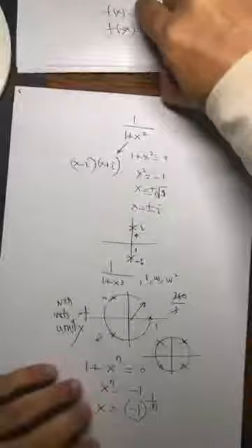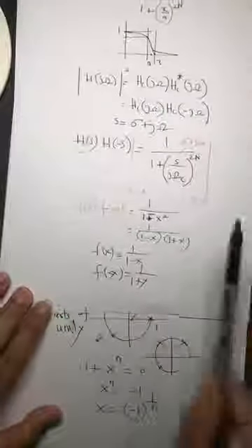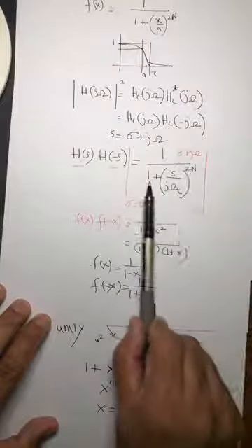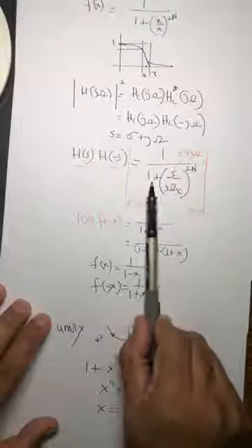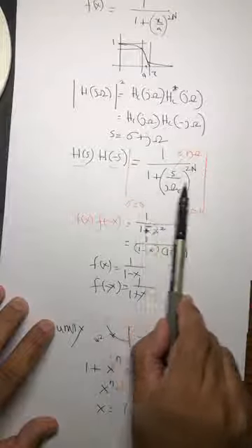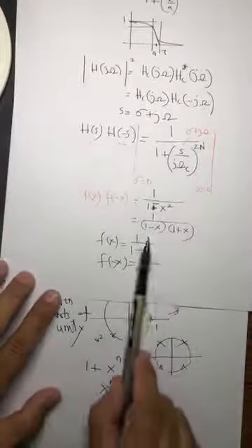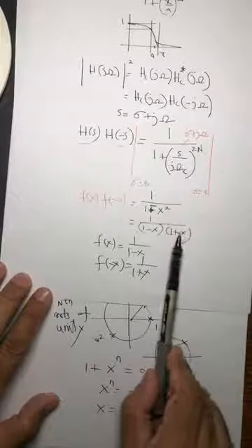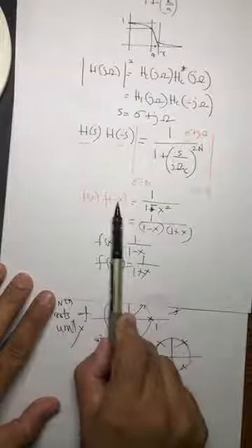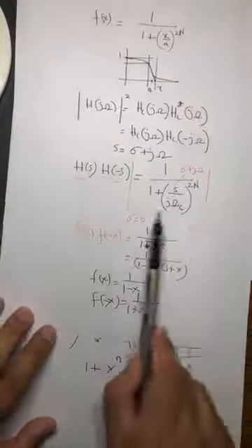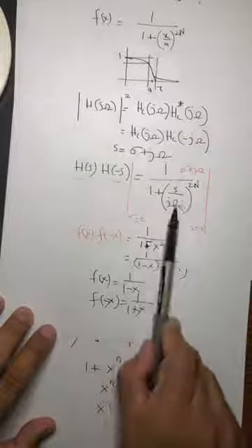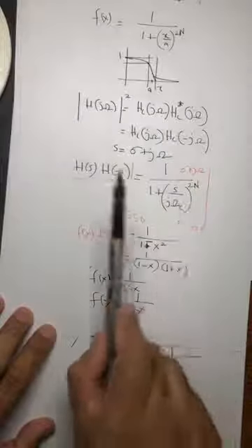So if you look at now this expression, and you want to find out 2n roots of unity. It is 2n roots of unity. Okay? Because it's an expression like this, you say, wow, I think I can figure this out. All the roots, because I need to find out roots as I did here. I first find out roots, then I split them into factors, and once I have factors, I give half of them to h of s and half of them to h of minus s. So I am precisely going to do the same. I am going to split. First I will figure out 2n roots of this expression. I will give half of these to h of s and the rest half to h of minus s.